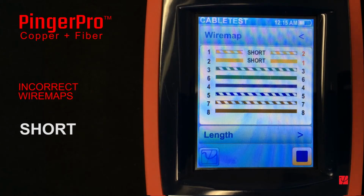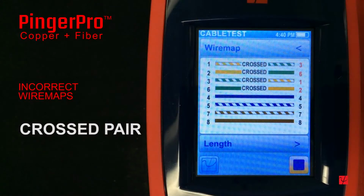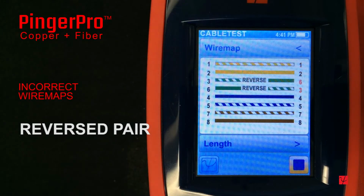A short pair occurs when a wire is physically connected to another wire within the cable or at a connector. A cross pair occurs when one twisted pair, like 1, 2, is connected to a different twisted pair, like 3, 6. The usual cause of a cross pair is a 568A termination on one end and a 568B on the other. A reverse pair occurs when wires within a twisted pair are switched on one side of the cable.